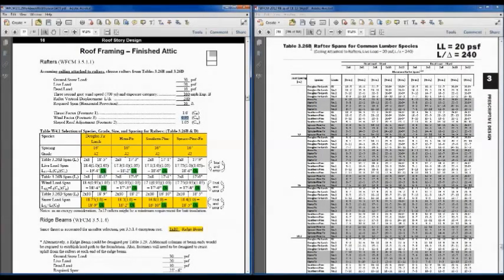So I'm back here to table 326B, and we're just going to take the first one. Just notice that we've solved this for Doug fir larch, hem fir, southern pine, and spruce pine fir, so no matter what part of the country you're in, you probably have one of these options here. The yellow indicates that all of these options work. We've got green here, which shows that we've made it work. Notice these little trial and error icons out here mean that this is a trial and error process. We may have to go to the span tables and pick a rafter span, but then once we adjust it, some of these adjustment factors are greater than 1, some of them are less than 1, so that may require a trial and error process.